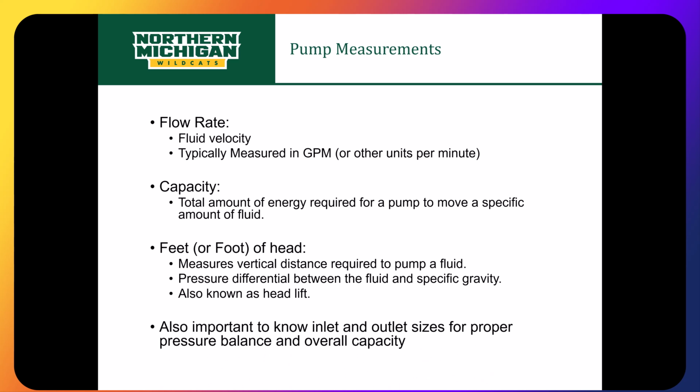The other thing to note on this, just for generic understanding, is inlet and outlet sizes are also important to know, because if we have incorrect sizes, there is a pressure balance and overall capacity issue. So for things like retrofitting and adding capacity or removing capacity, you want to maintain the balance within our water distribution system. And with that, that is a brief intro into pumps.